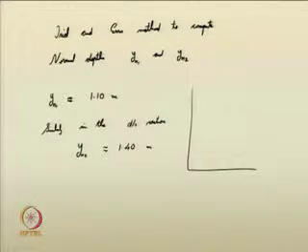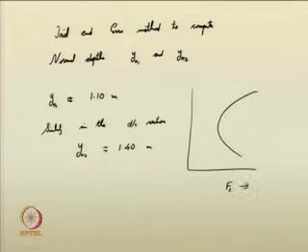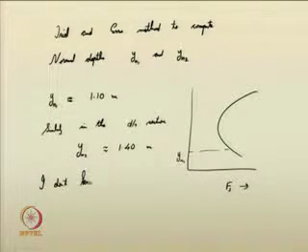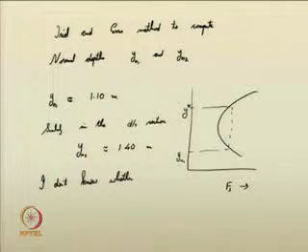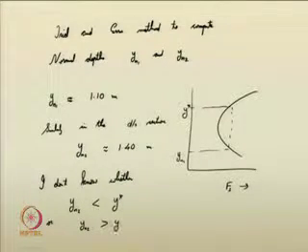Now, one can draw the specific force diagram. I am getting yn1 and I am getting yn2. At present I do not know whether yn2 is less than y star or yn2 is greater than y star, that you need to determine. I can now easily suggest the approach.